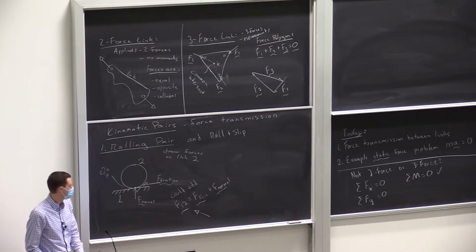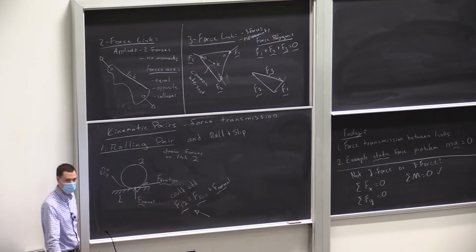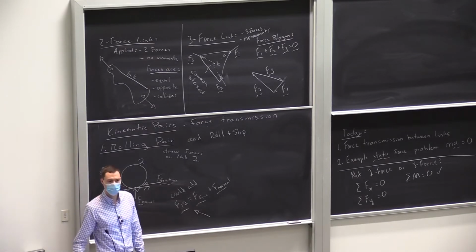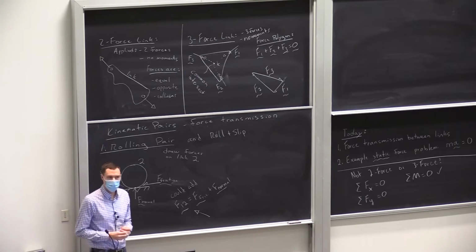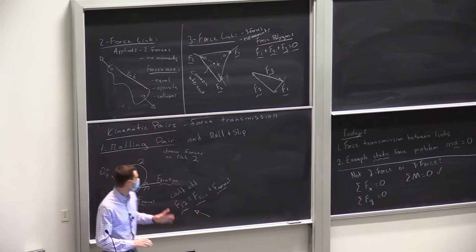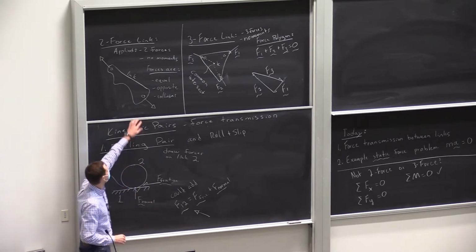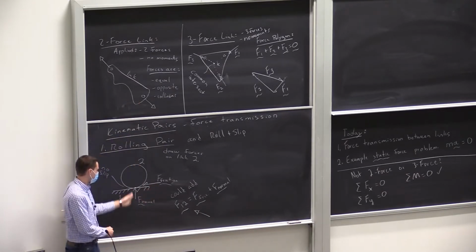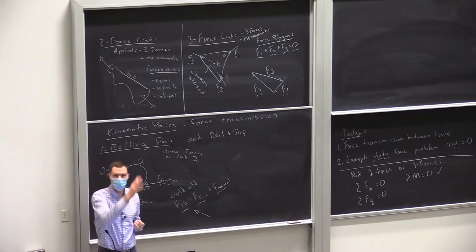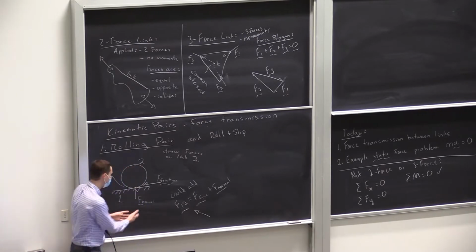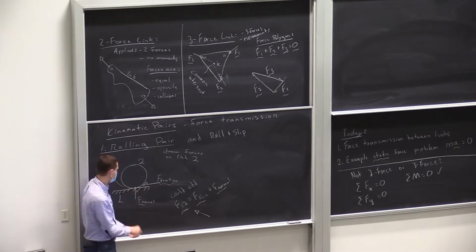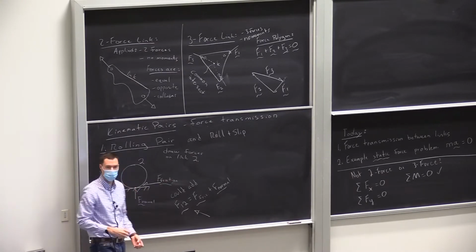Is it that the direction of friction, like it's not like something's gonna be in the same direction as motion, something's gonna be in the opposite direction of motion? Like, isn't it the direction of friction is not known always, right? Yeah, direction is not known. So everything that I'm drawing, even like these up here, these are directions that I define when I'm defining this vector. I call that thing F normal. And I just said it's up. It's pushing up on link 2, and friction force is pushing left.